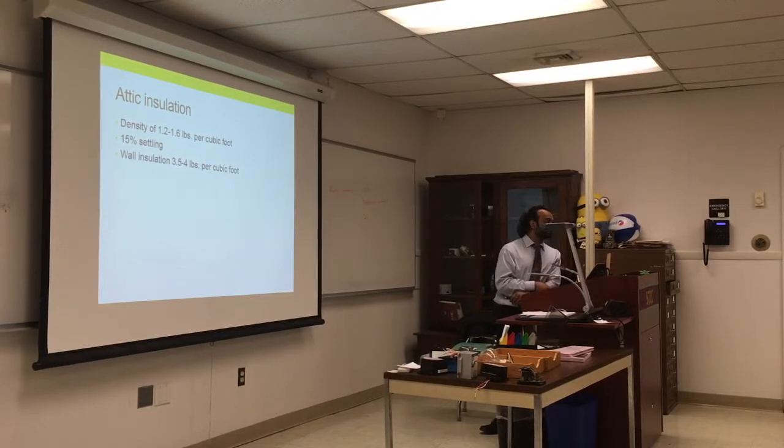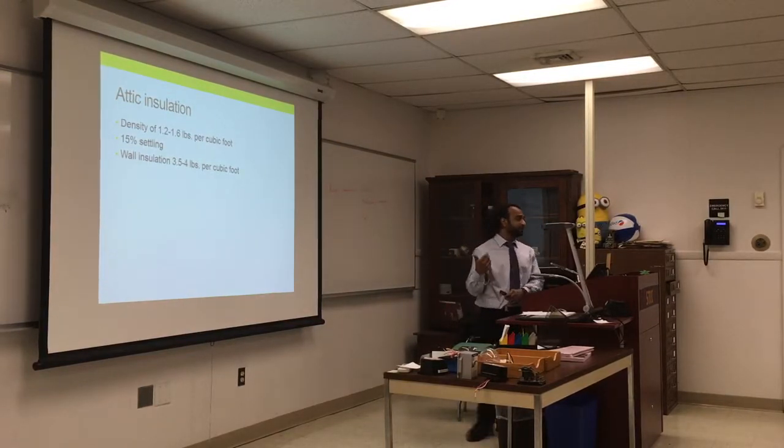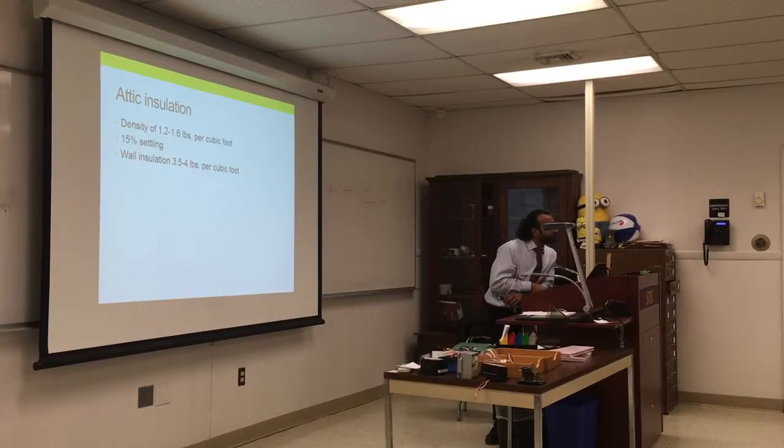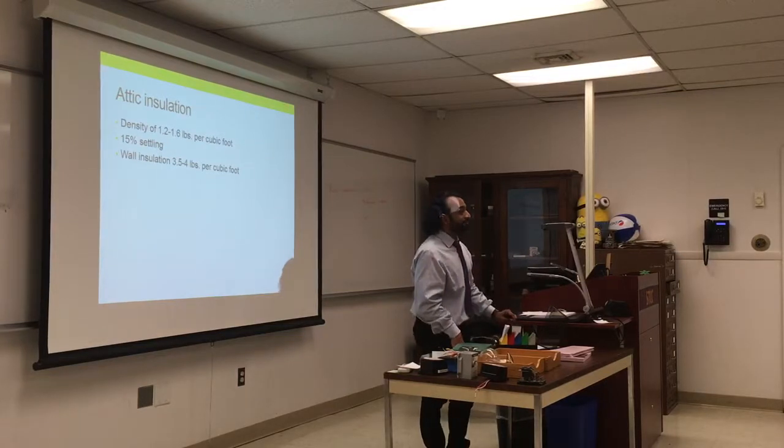So soffit vents are a quick fix? It's not like in the overhang of the house, you have the soffit vents that go from the attic. But you're saying if there's humidity, you're looking at. No, you should never vent your attic. Period.